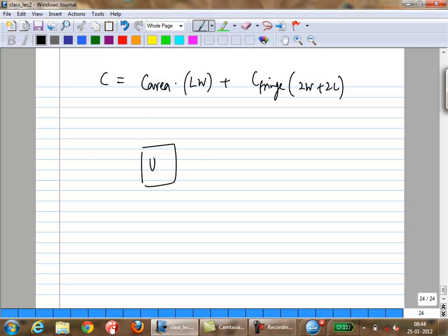Okay? So one thing you can do is to lay out the capacitance in terms of unit cells. So instead of using two of these, if I do this, instead of just using double the length, I lay it out as 1 unit, and I lay the other out as 2 units. Then definitely the capacitance will be a better multiple, closer to 2 than what you got in the first case. Okay? But now you are still going to have mismatches in the environment.